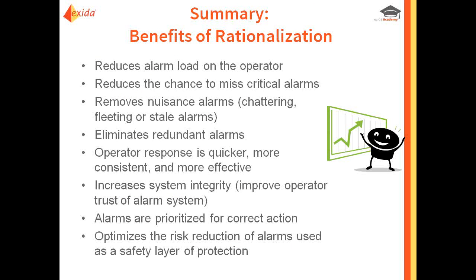Now, the benefits of rationalization, based on what we saw, what we did: you can imagine that filtering out alarms that don't belong will reduce the alarm load on the operator. It'll help get rid of nuisance alarms. We modified the deadband, or the on-off delay, and that would hopefully help. By reducing the alarm load, that helps make the system operate better for the operator. They have less chance that they will miss a critical alarm. They're also more likely to respond quicker and more consistently, not only because there's fewer alarms, but because we've also documented what they should do, and if we make that information available as an alarm response procedure within the DCS, then that'll help all the operators respond quicker and better.